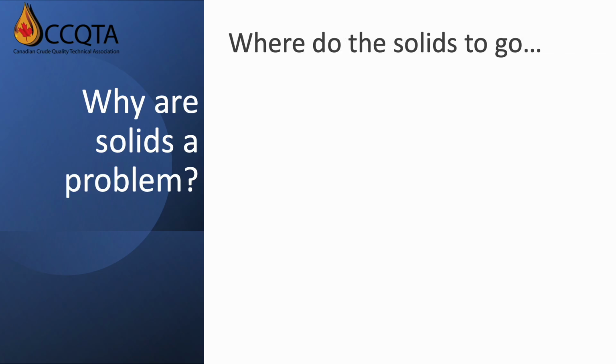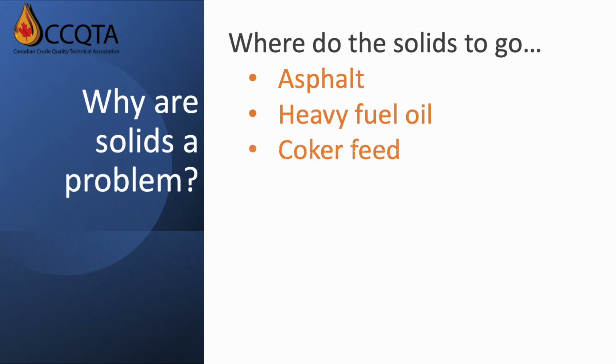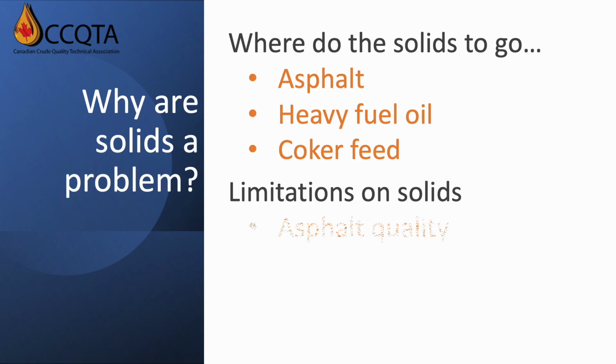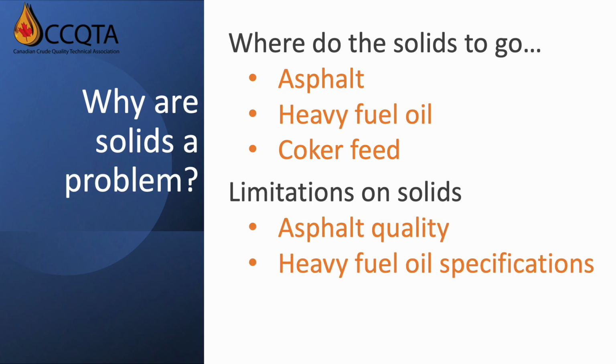Solids in the desalted crude really don't have a good place or product to go to, other than possibly heavier streams such as asphalt, heavy fuel oils, and coker feed. There are, however, limits to the permissible solids content in these streams. Asphalt quality can be impacted by solids. Marine heavy fuel oil has a limit on aluminum and silicon content.